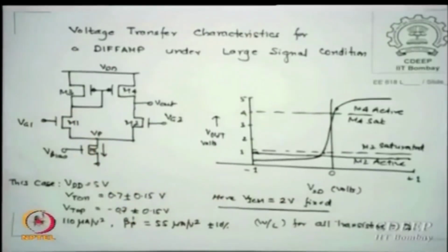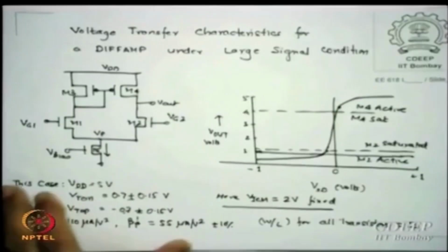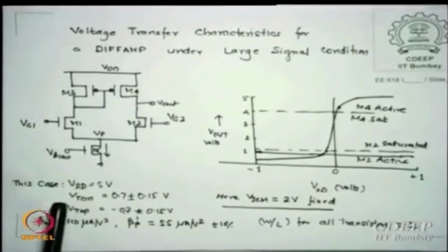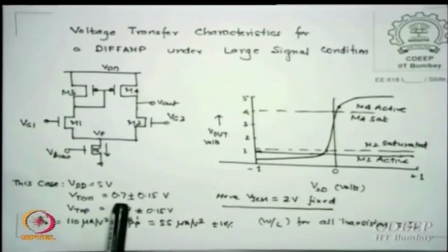So here is an amplifier again, same thing which I showed. Now let us say, I just tell you how the data can be given to you, this is not being used specifically here but just to show you. Let us say I have a 5 volt supply, this 5 volt supply has come from a 0.35 micron process. We used to use 5 micron. So in all the books whenever you see, barring the latest ones which may probably have a 1.2 volt supply, otherwise this is the data given by everyone. So I thought if at all someday you are going to read the book, you should have this. The VDD is 5 volt, VTO of NMOS, where O stands for without substrate bias, typically it will be 0.7 volt, let us say plus or minus, this is the tolerance you will get actually.